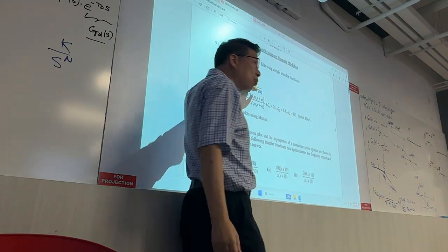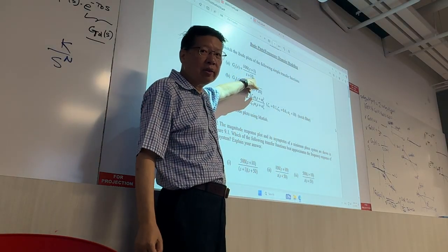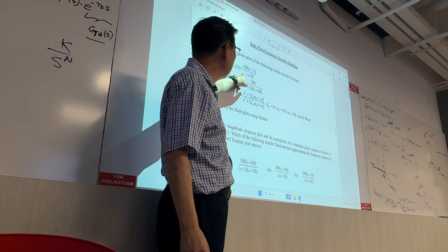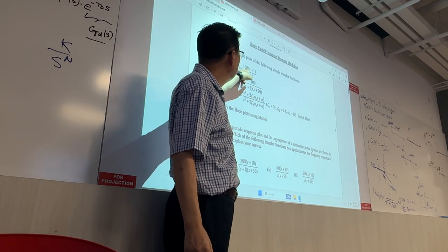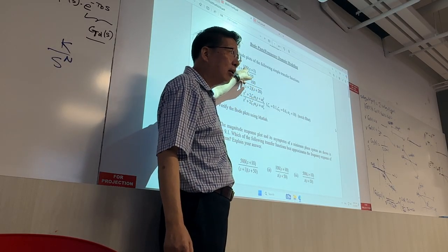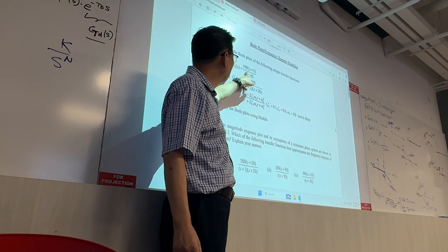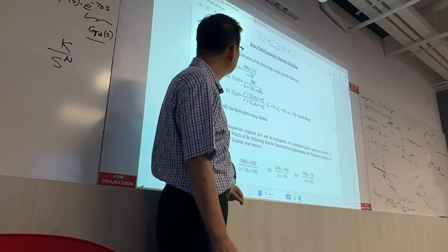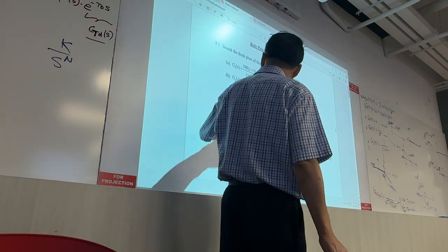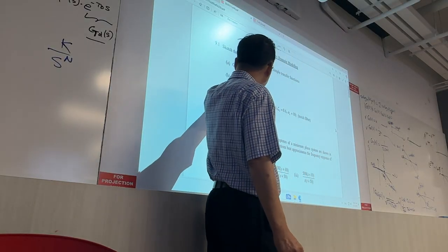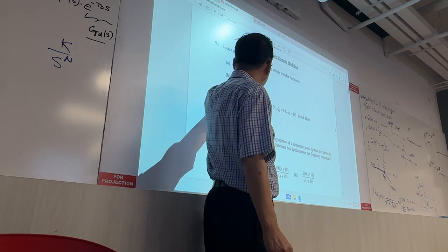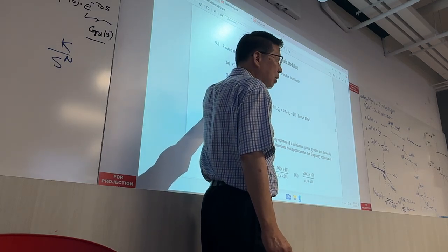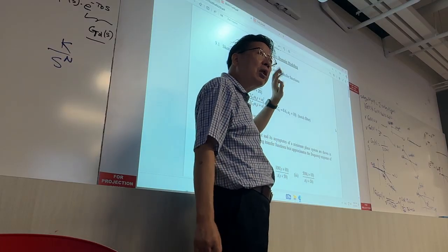The first thing you spot is this is not normalized. You need to normalize by pulling this 10 out, then this gain will become 10, right? And here you have 1 over 10. And then there's a 10 here, there's a corner frequency 1, and then there is a corner frequency 10, so only 3 basic factors.